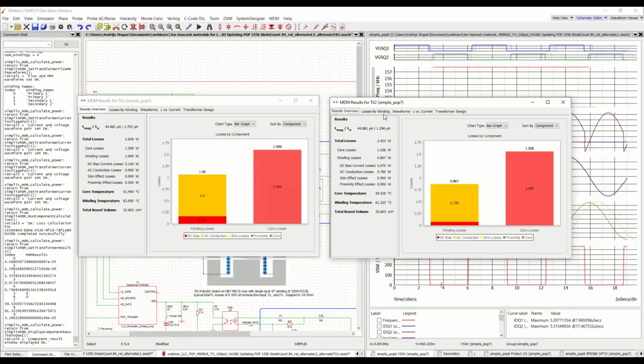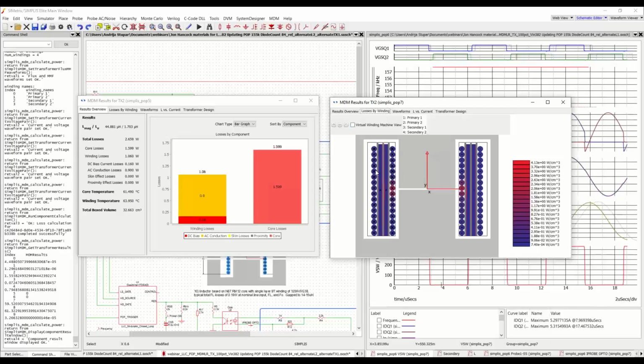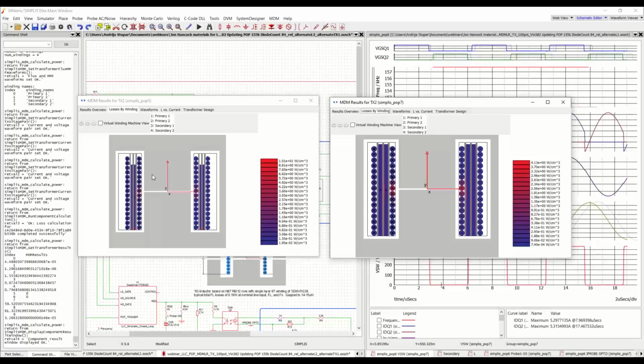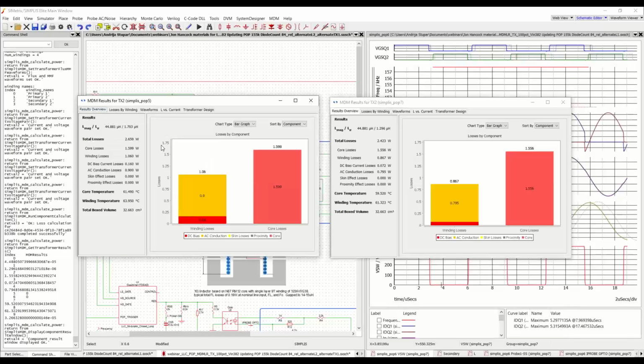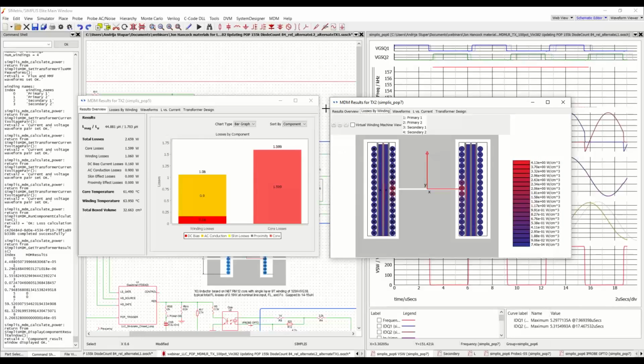Well, because we've added extra area, now we need extra length for all those wires that are wrapping around the center of the core, so there's no free lunch in that respect, and that is increasing our resistance while the extra cross-sectional area is decreasing it. And what we then get is a slightly lower loss number. So again, that's something where you would try to trade off whether this decrease is worth the increased cost of more copper here and longer wires.